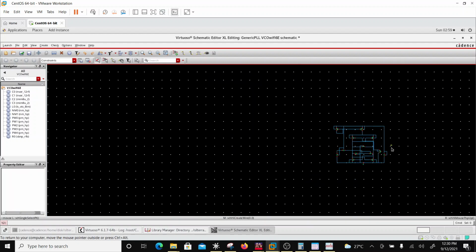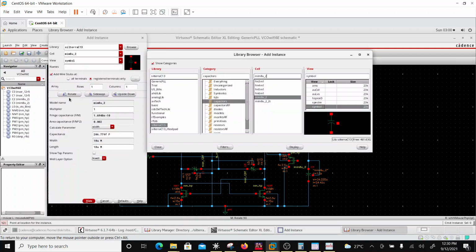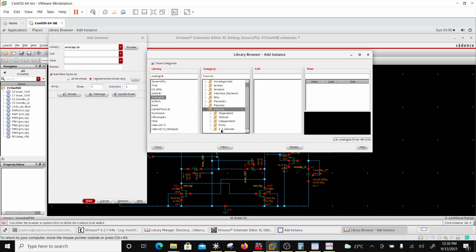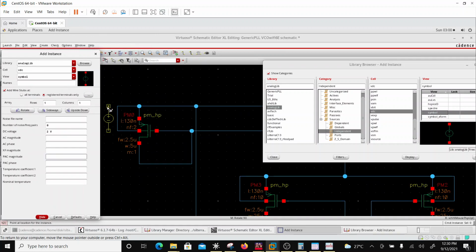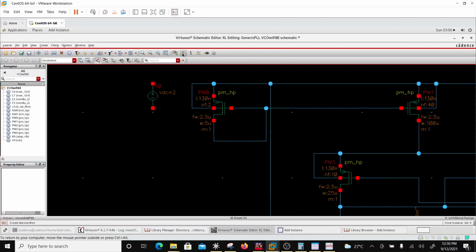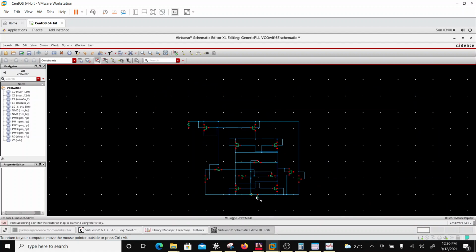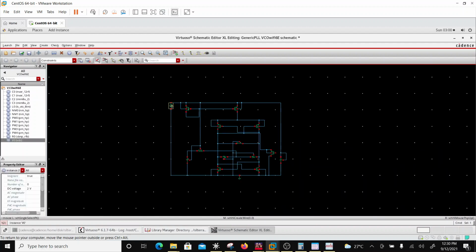Okay, so this is our VCO core, and I want to pull certain current out of this. So I will insert IDC. Okay, VDC, and I want to operate this from 2 volts. Sorry about this. So it's operating from 2 volts. Let's get this one. I can put the common ground, doesn't matter. And then I need a control voltage, so I'm going to put 0 volts here. So I'm going to copy this.